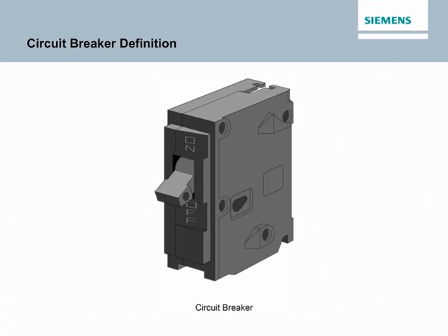Circuit breakers provide a manual means of energizing and de-energizing a circuit and automatic overcurrent protection for that circuit. Unlike fuses, which must be replaced when they open, a circuit breaker can be reset once the overcurrent condition has been corrected. A simple push of the handle to the off, then back to the on position restores the circuit. If a circuit reopens upon reset to the on position, a qualified electrician should be consulted to determine the problem.